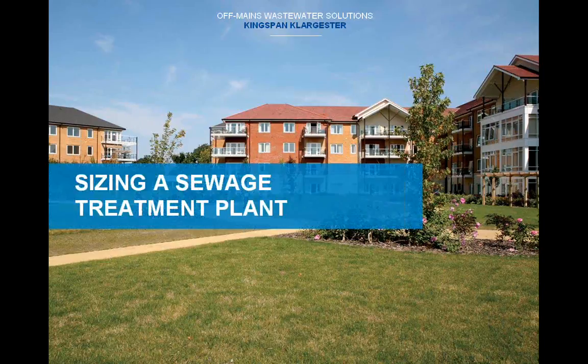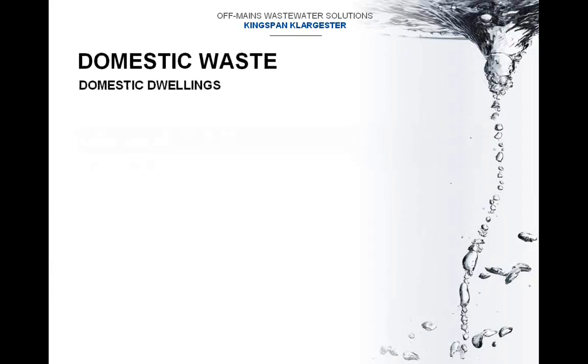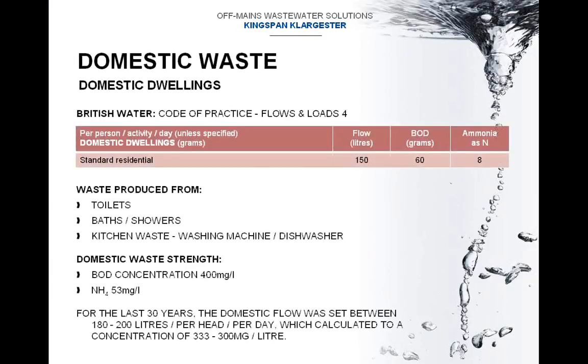Sizing a sewage treatment. Sewage is split into 2 parts, domestic waste and commercial waste. Dealing with domestic waste first, this is basically the flow as you would have in a normal household. The flows range from 150 litres per person per day, using an organic load of 60 grams of BOD and an ammonia load of 8 grams.